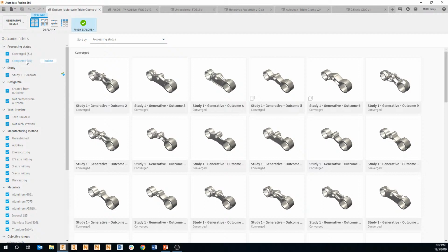And this is actually really impactful for us. If we had set a plastic material in this situation that wouldn't be strong enough, generative will try and try and try across all of its iterations to reach that solving criteria, but it may fail, coming back as completed. You'll also see all of these thumbnails on the screen. As we hover over one of the thumbnails, you'll see this timeline slider at the bottom. As we drag this from left to right, you can see all of the iterations that generative actually went through to produce that final component.